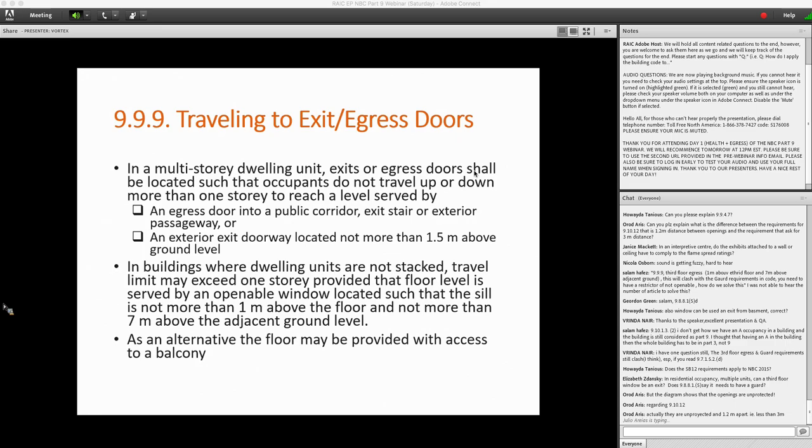So we have a few more questions to answer, just about 4 more. Question 40. Third floor egress, 1 meter. How do we solve this? I believe I answered this. So there are some waivers. If the sill of the window is more than 450 millimeters, you do not have to provide a guard.